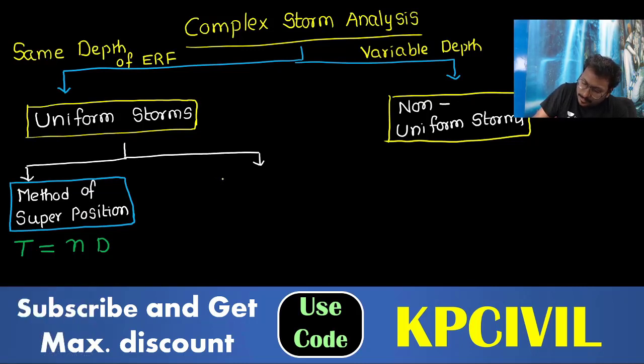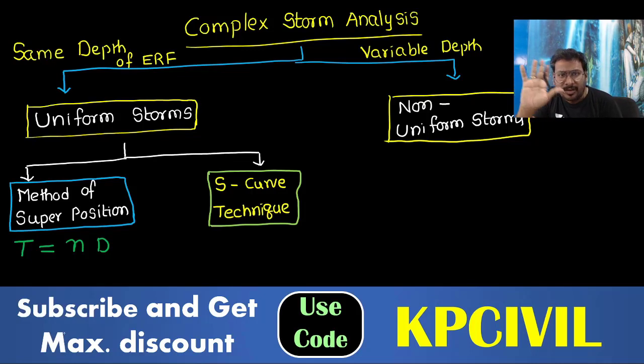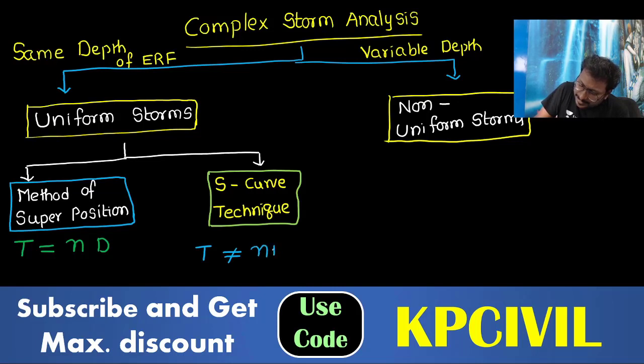Unequal storms: S curve technique, S hydrograph, S curve analysis, S curve technique, all are the same. For example, you have a storm duration of 5 hours and your available hydrograph is 2 hours. Will you divide a 5-hour total time into equal periods of 2 hours? Not possible. So T is not equal to ND.